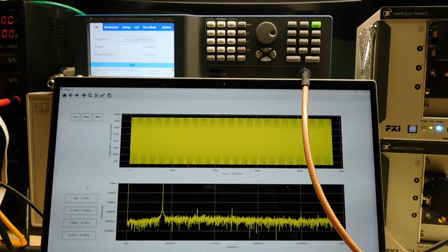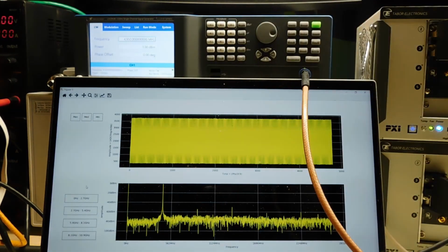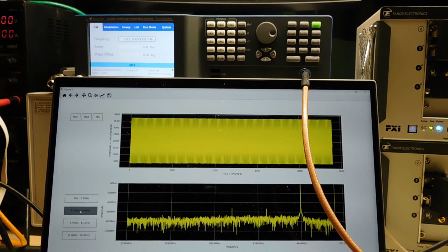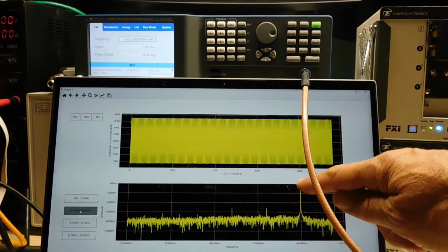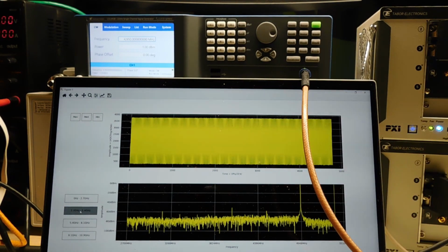We change the center frequency to 5 gigahertz, and what we end up with is a signal here at 400 megahertz. If I just invert the display and change the axis, you can see now that it lines up pretty well in the second Nyquist zone with exactly the frequency that I typed in on this line here. And then we can do the same again, going up another Nyquist zone,